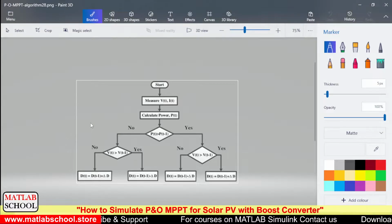So this is the MPPT model that we are going to implement. This is the P&O, Perturb and Observe type of MPPT. To implement that, we need to sense the voltage and current initially. From the sensed voltage and current, we calculate the power. The current power will be compared with the previous power. P of t is the current power and P of t minus 1 is the previous power.